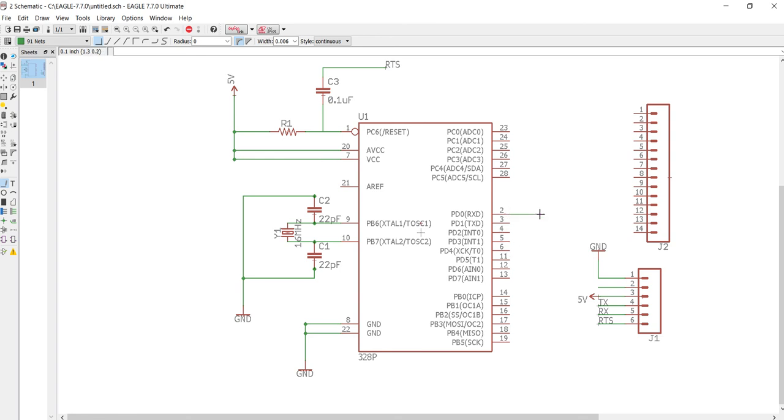we definitely know in order to program this thing, we're going to need to have our RX and TX, right? We want to work with that. And in order to get a bootloader into this, we're going to need to have access to the SPI pins here. So we're going to want to break out. We'll use these pins down here, and we'll start with that.